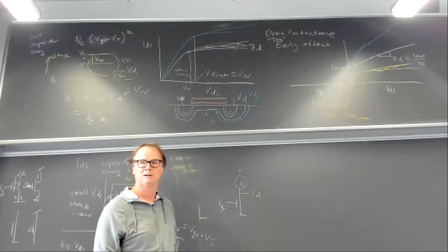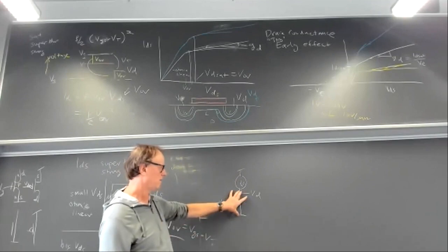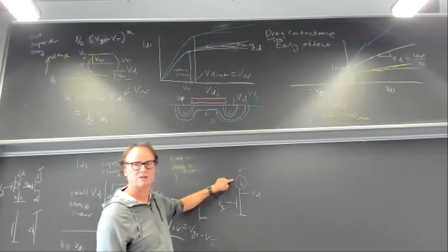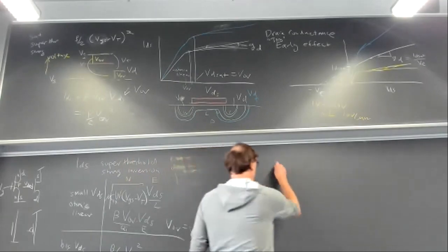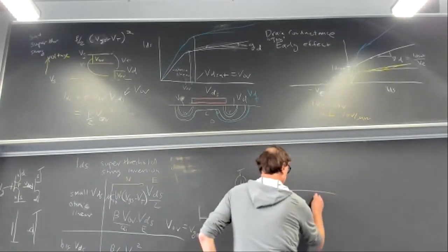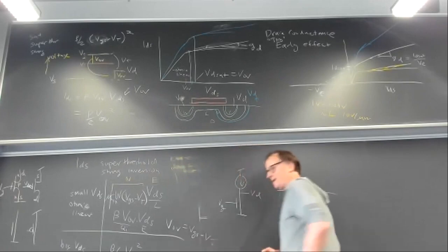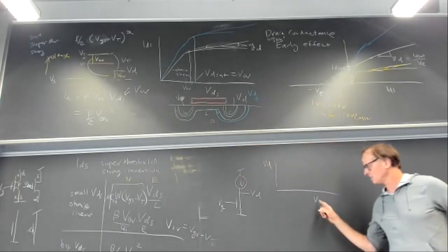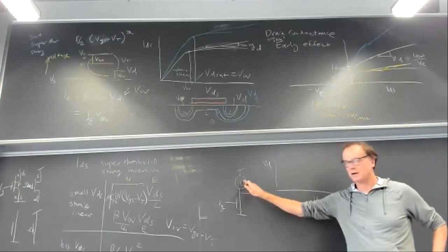Is it clear? In other words, there'll be a certain small region of gate voltage where the current wants to sink about what you're sourcing here. That's where all the action happens. So if you plot this drain voltage as a function of this gate voltage, what will you get? Well, for small gate voltage, this will be turned off, and the current source will pull the voltage up.